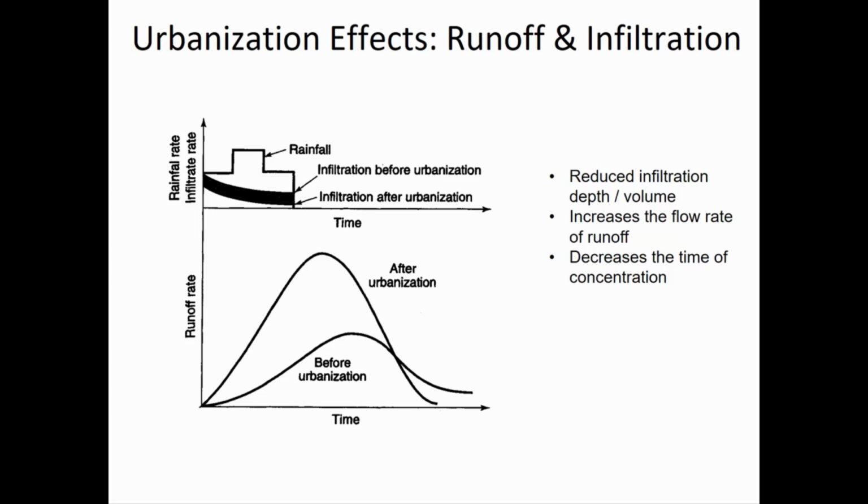Okay, so conceptually what this means is that before urbanization we had lots of infiltration for the same amount of rainfall, assuming that stays constant. If you had more infiltration back in the olden days, before we paved over everything, then during those days there wasn't as much rainfall excess as there is now. So developments like that Amazon customer service center, that used to be natural land. You put a big warehouse and loads of parking up on that hill, then the people downstream of that hill are going to see more flooding than they used to.